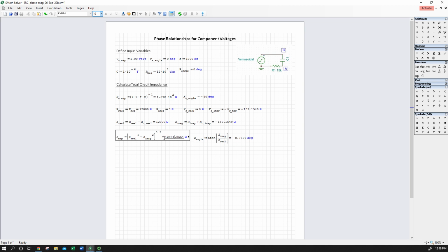Okay, that is actually something that would make sense when we put together with the fact that we have a very, very tiny contribution from our capacitive reactance in our magnitude of our total impedance. So we're on the capacitive side. We have a negative impedance angle. If we had an inductor, we would have a positive number. So that's as expected, and that's because our Z imaginary is negative. So A tan of a negative value is going to be down in that lower quadrant. But it's less than 1 degree. So it's almost pure resistive.